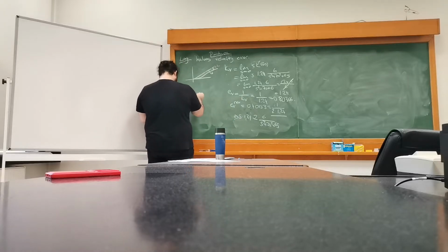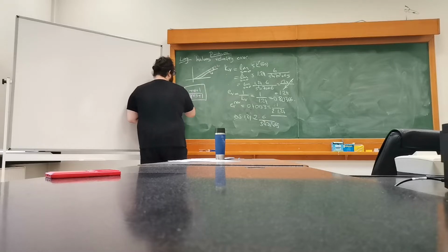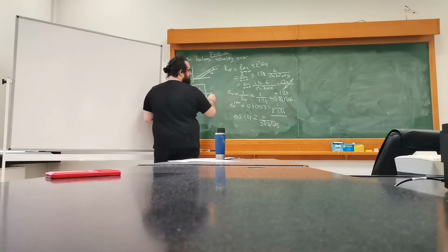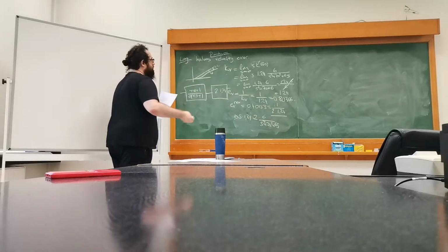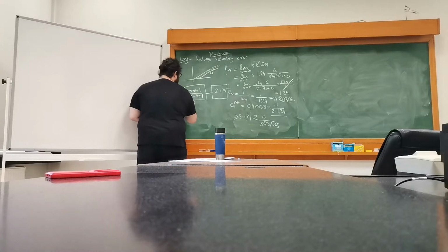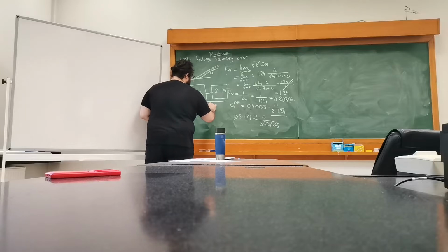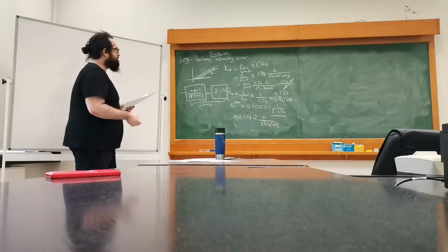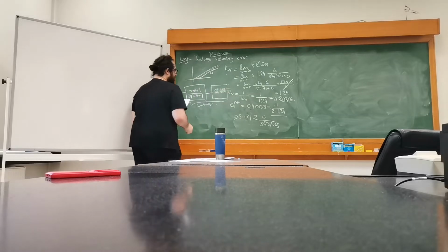Let's add tau s plus 1, alpha tau s plus 1. So this is the lag part. And then I have a certain gain. In this case, it is 2 times 1.24. And then we have the system. So this is basically the whole controller part. So instead of this, maybe we can use 2.48 roughly.